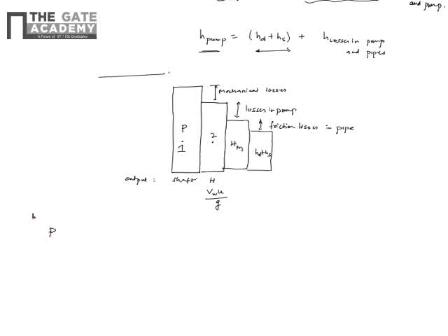So there are a couple of things. First, the shaft power, and then you have the mechanical losses. So what you get is this head, which is rho Q into H, that is delivered, which is rho Q VWU by G. This is the head that is delivered by the impeller. Now you have some losses in the pump, in the casing and other friction losses in the pump. So what you get at the outlet is the manometric head. We call that manometric head, which is less than this rho Q VWU by G, at the exit of the pump.